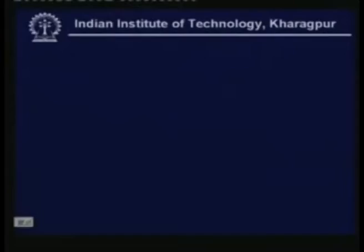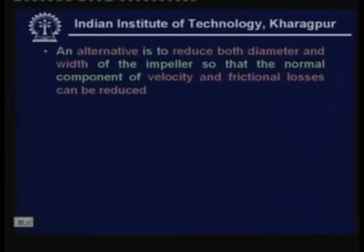Now let us look at other options. What are the other options? An alternative is to reduce both diameter and width of the impeller simultaneously, so that the normal component of velocity and frictional losses can be reduced. If you want to reduce the frictional losses, you have to reduce the length of travel. One way of reducing the frictional loss is to reduce the length of travel. That means you have to reduce the diameter of the impeller. That means you have to simultaneously reduce the diameter and width of the impeller, so that the mass flow rate gets reduced.